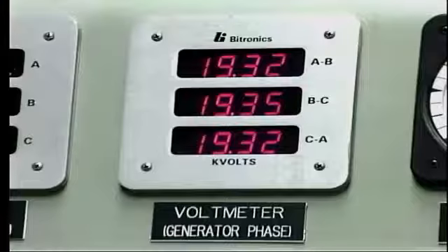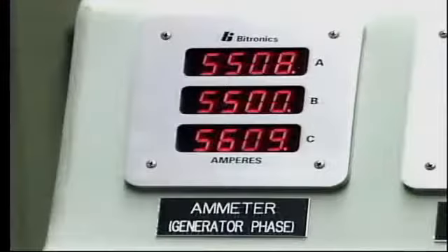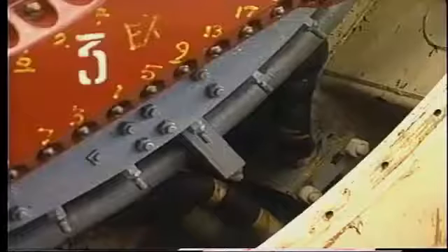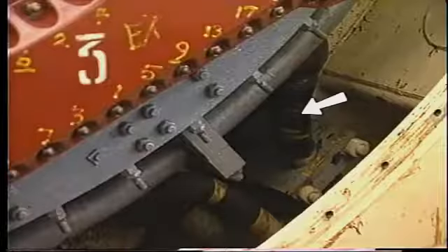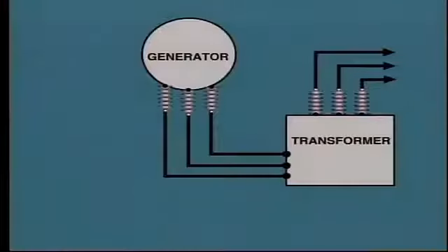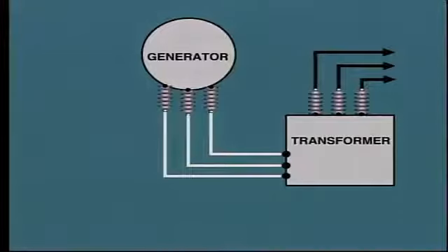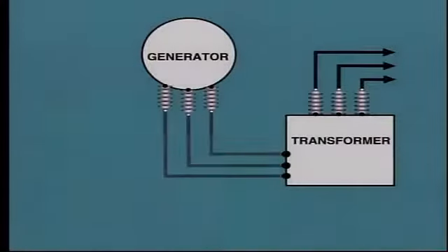The stator conductors are connected together in various series and parallel arrangements to produce the rated terminal voltage, typically in the range 11 kilovolts to 25 kilovolts, and rated output current, which may be several thousand amps. The stator windings are connected to the terminals, usually located at the bottom of the generator. Outgoing conductors are connected to these terminals in order to carry power to a bus or a power transformer, and perhaps to an auxiliary transformer.